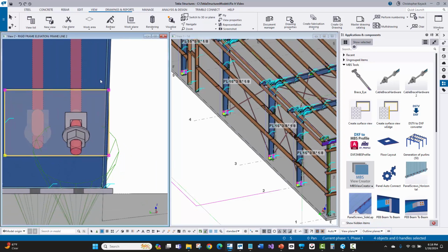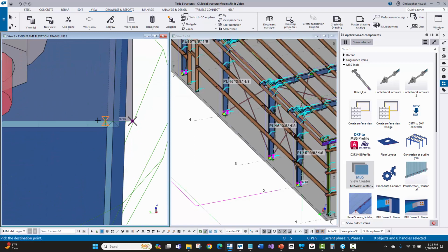Now what I'm going to do is I'm going to use that basically Alt command and just move that over. So what I'll do is I'll just hold down Alt, window left to right around those 2 grip points, use the move command, and then I'll just move this over. Now I'm just going to kind of eyeball this and see how far do I need to go. I probably need to go 3/4 of an inch or so. So I'll just do 3/4 of an inch there.